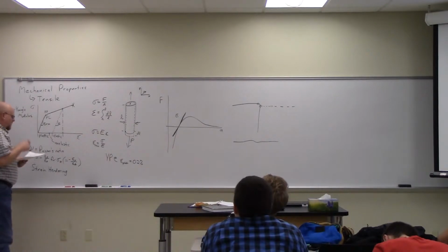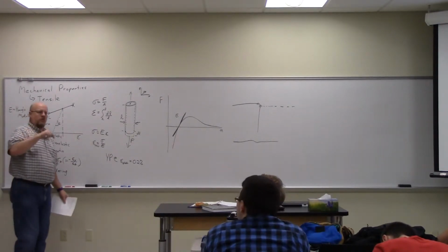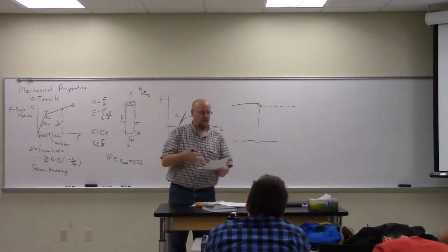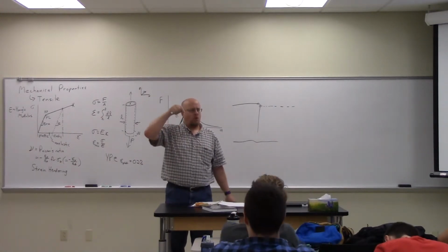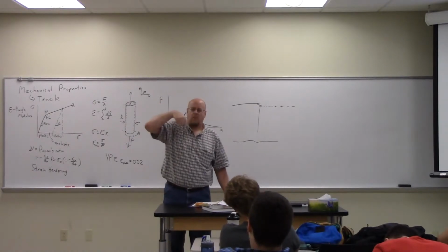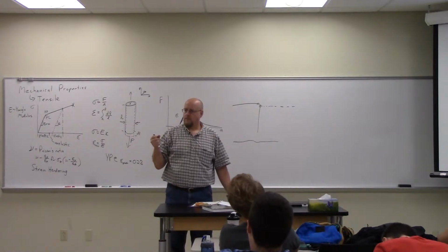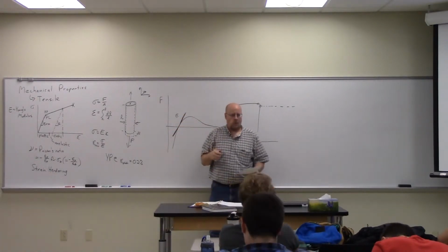hardening. And that's actually typically measured, this hardness is usually measured by the resistance to penetration. So in other words, if I want to characterize a piece of material that I have hardened, I would measure it by putting a known indenter, like a known little ball, a hard steel ball, on it with a fixed load and see how big of a dent it makes. The harder it is, the smaller the dent. So you measure the hardness by measuring the indentation. Okay.